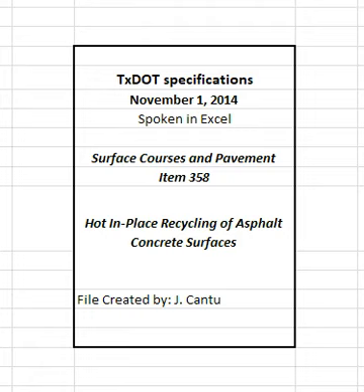4.7 Compaction. Uniformly compact the pavement to contain between 3.8% and 8.5% in-place air voids. Furnish the type, size, and number of rollers required for compaction as approved and meeting the requirements of Article 210.2, Equipment. Use a pneumatic tire roller to seal the surface unless excessive pickup of fines occurs. Use additional rollers as required to remove any roller marks. Use only water or an approved release agent on rollers, tamps, and other compaction equipment unless otherwise directed.